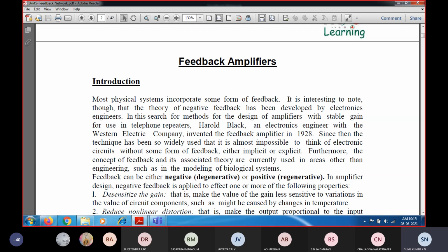And based upon that, we have seen the alternative arrangement of the Colpitts oscillator, another configuration. One best example is the Pierce oscillator, which is the same type of Colpitts oscillator. Colpitts oscillator means two capacitors C1 and C2, along with the crystal, connected in parallel to the CMOS inverter amplifier, which provides a sustained oscillation. Since the output is fed back to the input with a feedback resistance, it provides a continuous oscillation based upon the crystal oscillator along with the Colpitts configuration. So that is about the oscillator topic.